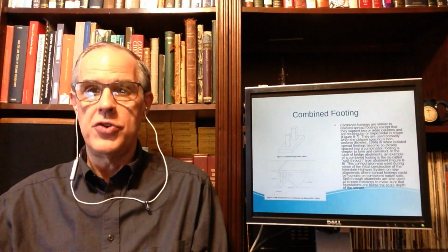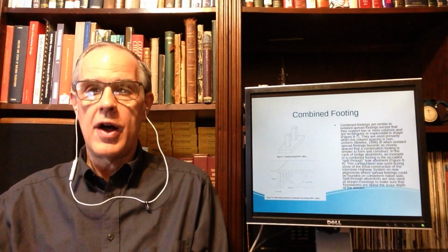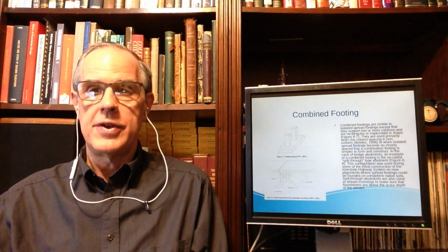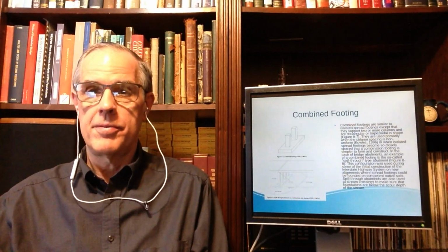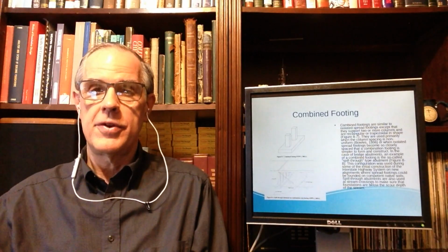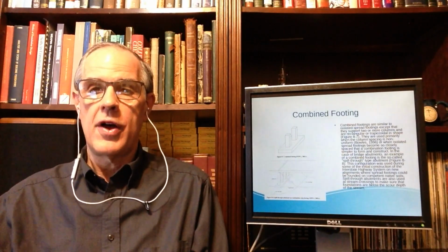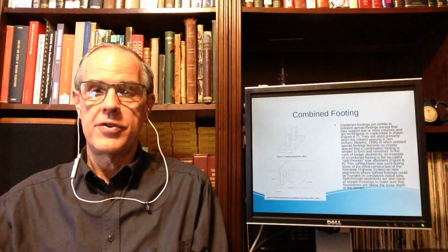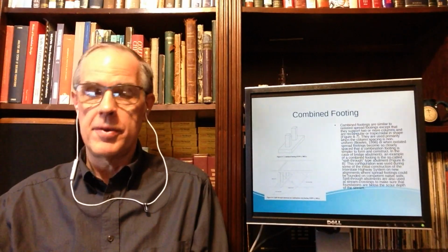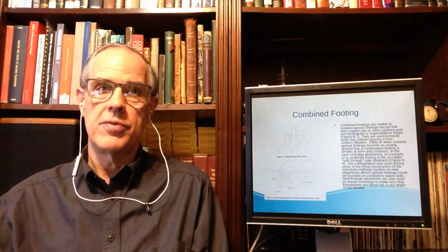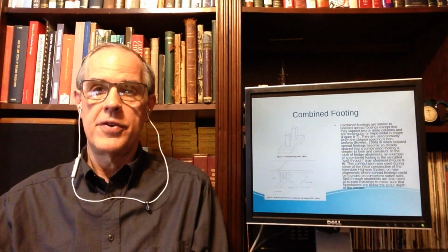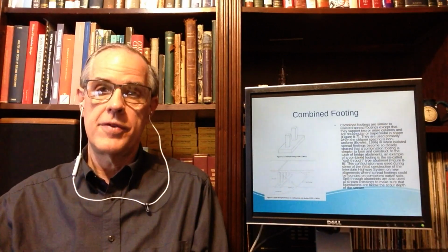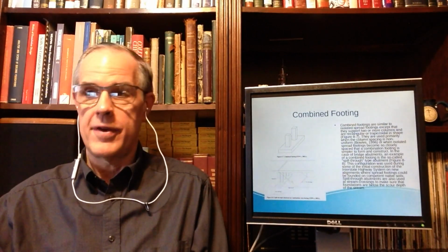One way you can deal with that is for geotechnical purposes. Now, structural is a whole different ballgame. For geotechnical purposes, if you can do it, you can resolve all of the loads into a single load. And it's entirely possible, if the footing and the loads are all nice and concentric and everything works out, that the analysis of the footing is no different than it is with a singly loaded continuous foundation, or finite foundation as well.